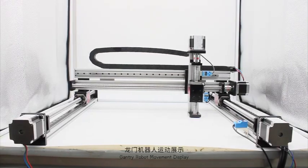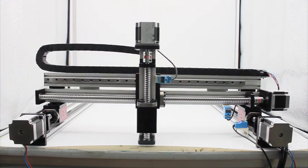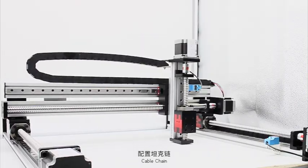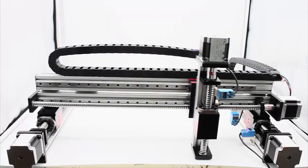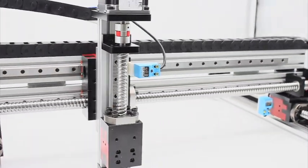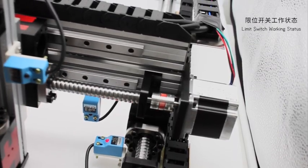This is a robot you can see, which is capable of moving in all x, y, and z axes. You can see the up and down motion belongs to the z-axis, and right and left belongs to the y-axis or x-axis, any axis that we can assume, and front and back belongs to another axis. So this is called a three-axis Cartesian gantry. Here is one more interesting thing: you can see how rotation is converted into up and down or linear motion. A screw is rotating, and when it is rotating in different directions, the arm or the object is going up and down and left and right.